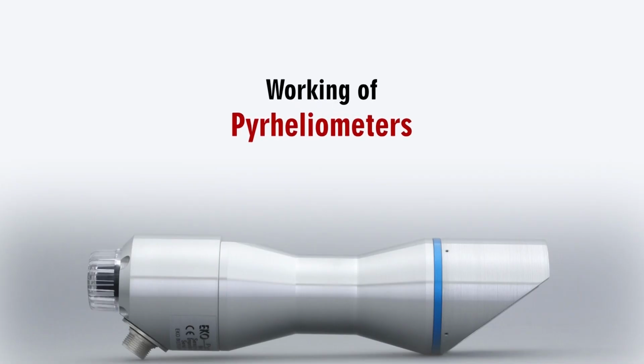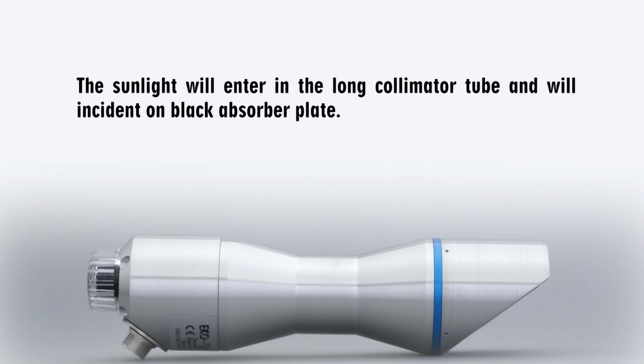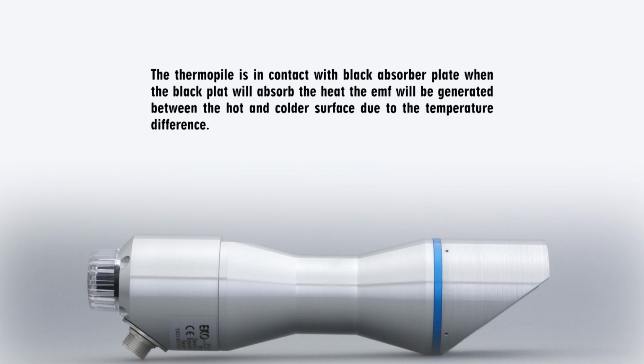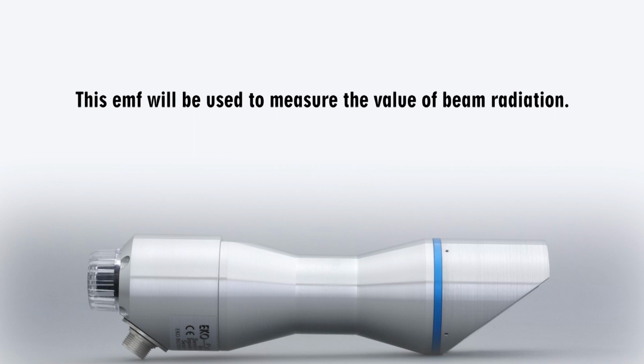These instruments are especially used for weather monitoring and climatological research purposes. The working principle of this instrument can be understood like this. The sunlight will enter the long collimator tube and will be incident on the black absorber plate. The thermopile is in contact with the black absorber plate. When the black plate absorbs the heat, an EMF will be generated between the hot and colder surface due to the temperature difference. This EMF will be used to measure the value of beam radiation.